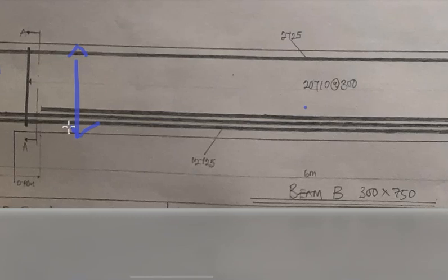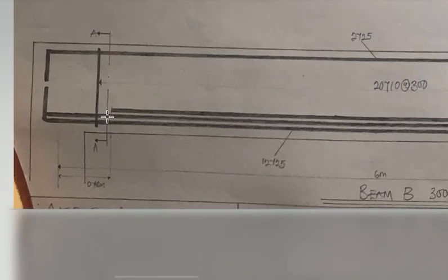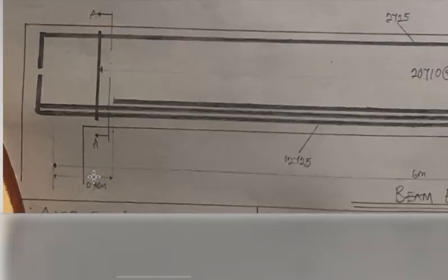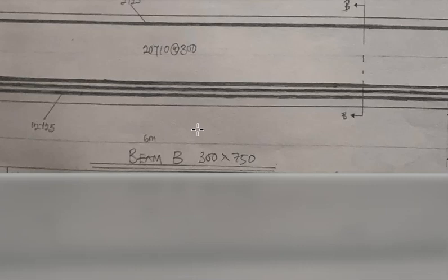So we have 6 bars, and I did 4 on the first layer and then 2 on the other layer. That's 6. So that's complete. This beam is quite different from a slab. Our beam curtailment starts literally from 0.08 L. L is your beam span. So 0.08 of 6 meters is 0.48, and that is what we just did there.